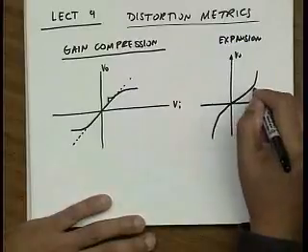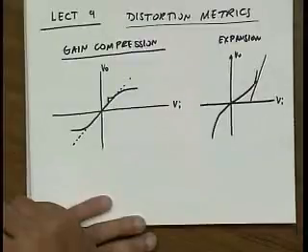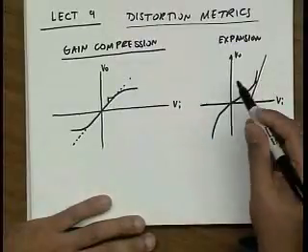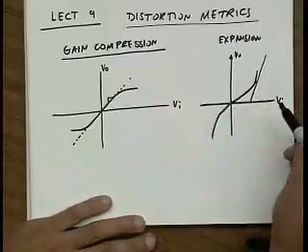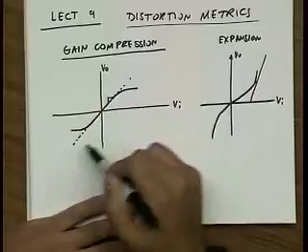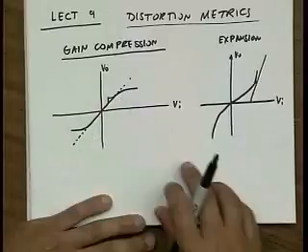Now you can also have expansion, less common, but gain expansion means that actually this thing might look like that. So the slope increases at high level inputs. Now even though you might observe this for small inputs, eventually if the input gets large enough you will experience compression, because most systems eventually will compress, let's say at VDD, the power supply voltage.